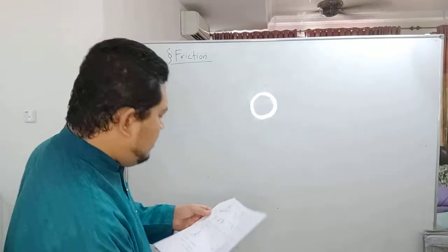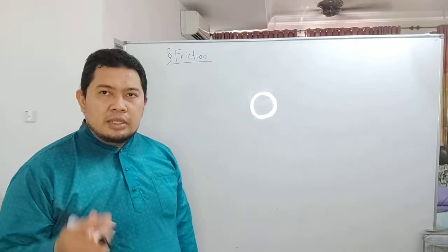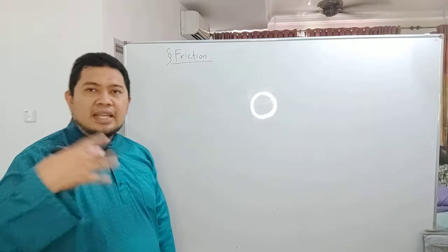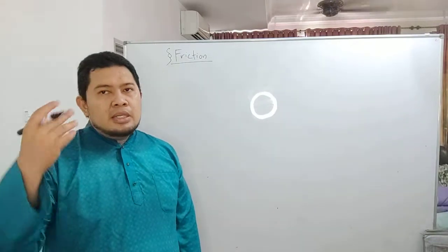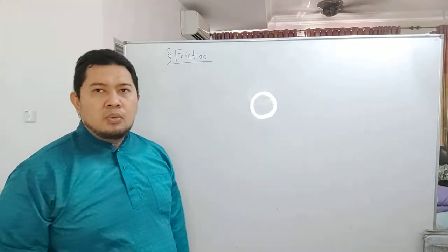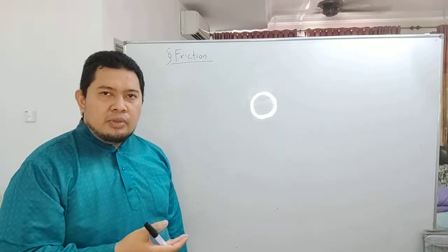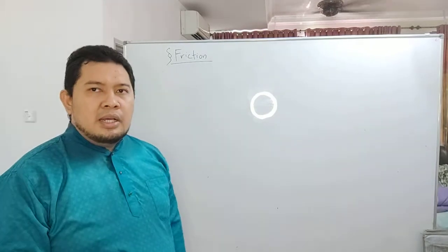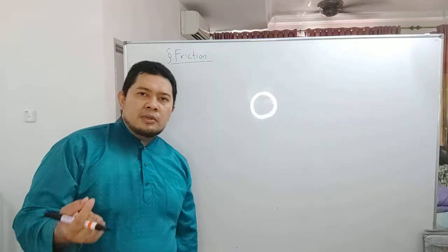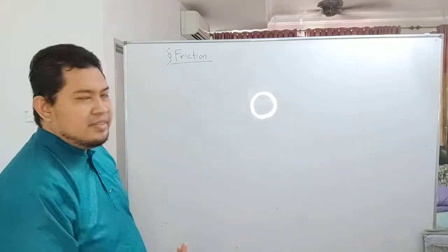Continuing with our lecture. Remember, the normal force needs to be perpendicular to the contact surface. If you have an inclined surface, the normal force, which on a flat surface is similar to the weight, must be calculated along the direction perpendicular to the surface, so the normal force should be lower compared to the weight itself.